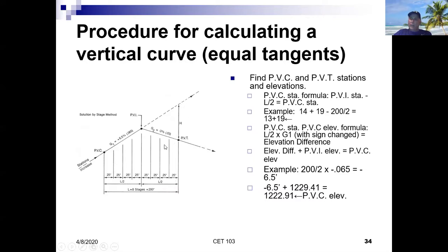So in finding the key components of a vertical curve, our vertical curve would come right here and go along this way and drop back here. What we would be looking for when doing a layout by equal tangents, we would actually be looking to slice our vertical curve up into pieces here, and then determine the elevation at the pieces.